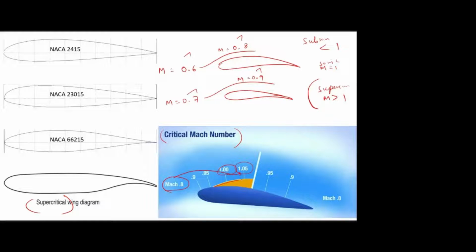So we are getting a small supersonic region over the airfoil. Locally we are getting one small region. So once there is a supersonic flow, then there will be a normal shock. Okay, so this white color shows the shock wave, and shock waves are compression waves. Compression, you know, means the velocity will be decreased and pressure will be increased. Compression wave. So what happened? Behind the wave, we are getting high pressure.